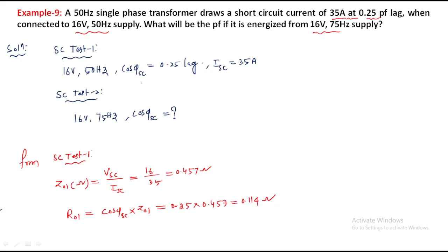So you all know what is the reason to get less power factor under SC test? Because the frequency is reduced, that's why we are going to get the change in power factor. We all know the observations. We have provided I rated and F rated, but we are going to get the variations in power factor with the variation in the supply frequency, right?